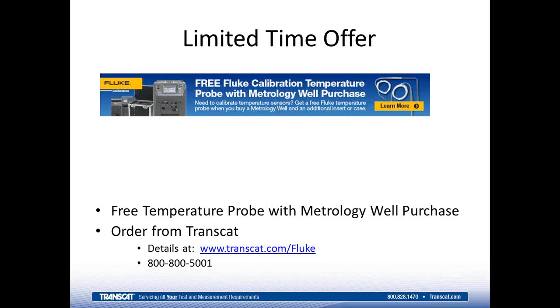It really comes down to a matter of risk. If you're using an RTD in an environment where an out of tolerance condition or a failure could be a real problem for you, then you might want to consider reducing the calibration interval, or at least doing an interim check more often.